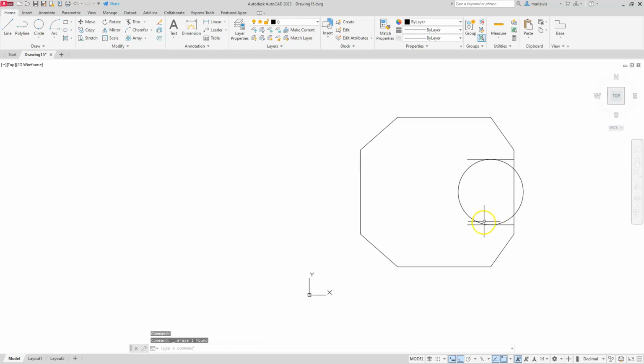The next thing I need to do is make sure that I offset these lines going down 5. Let's see, do I have my vertical line going here? Let's do one more thing. Let's go ahead and use our construction line. So I'm going to go to construction line, I'll choose the vertical option, and then I'll select this endpoint. Okay, and that's going to give me the basis for when I create the rest of these.